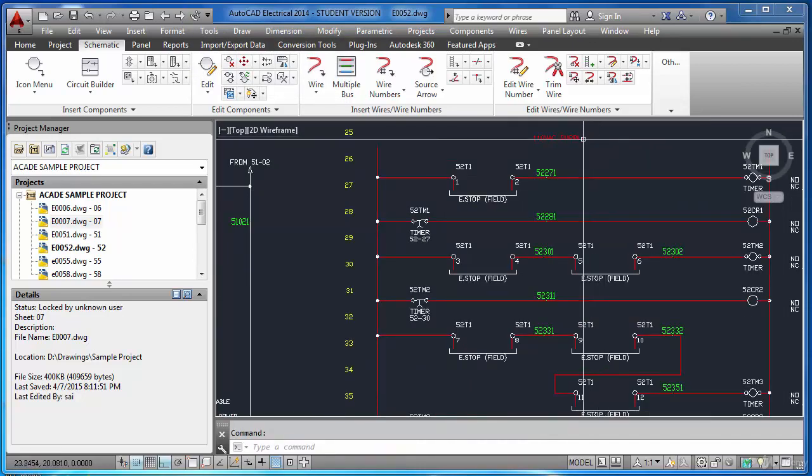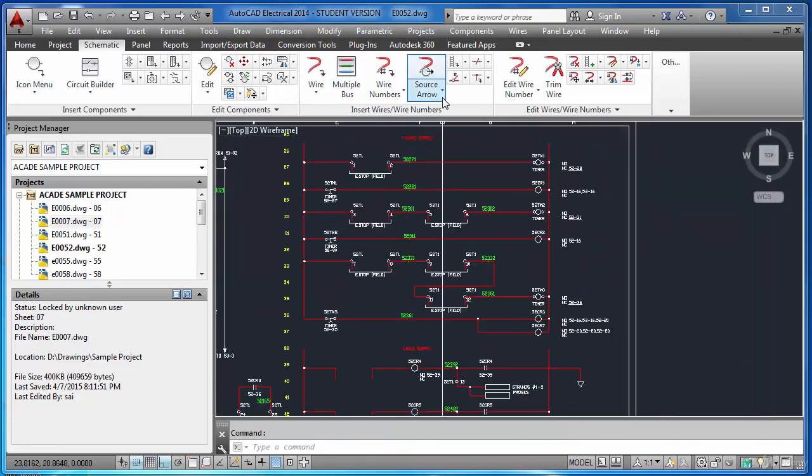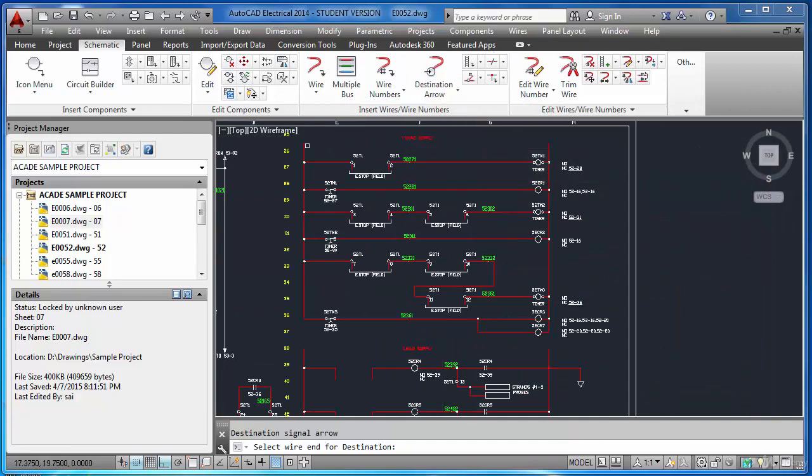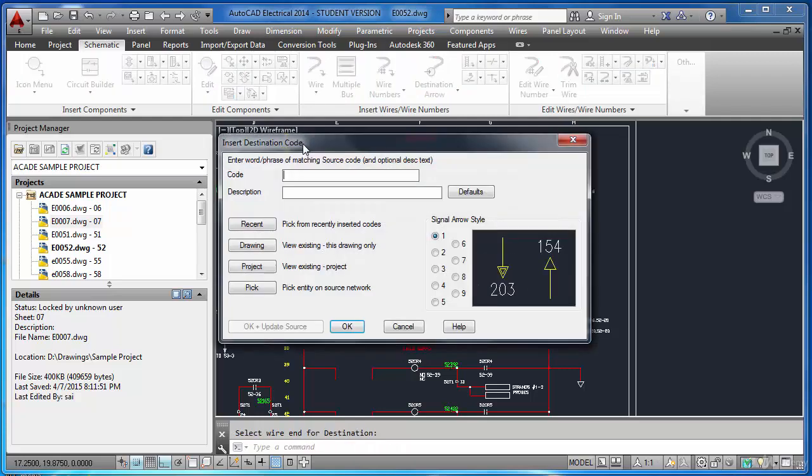I know here it is 110 volt. Here I will put a destination arrow. This is my phase. You should always leave phase in this way, I mean that will go to the field and return from the field. Neutral will directly go to the coil. 52 110 P1. Okay.